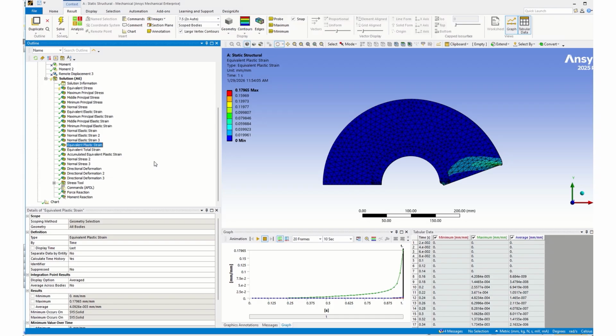Even though our equivalent plastic strain plot shows that it is not fully plastic, we've hit that load based on a force or load deflection plot. ANSYS is not able to compute plastic strain unless your stress goes over the yield strength.